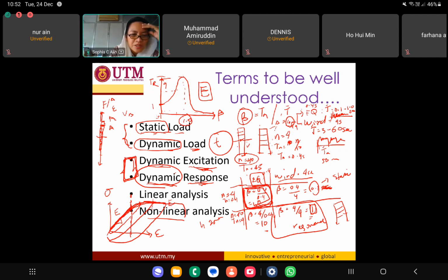So from this point to here, we call this linear, because according to the modulus of elasticity you can represent your material here: whatever force you give, the moment you release it, it still goes back to the original position because it is still proportionally linear. After the yield point, if I impose more load, it cannot go back anymore, meaning some part of the material has already yielded and is damaged.